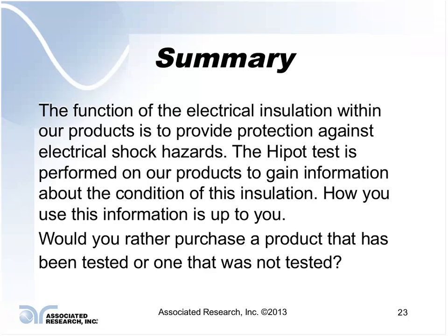With longer durations, corona can degrade the insulation. It can finally eat through the insulation and create a failure itself. So, depending upon how long you're doing the test, that can in fact be more destructive than just doing a short Hipot test.